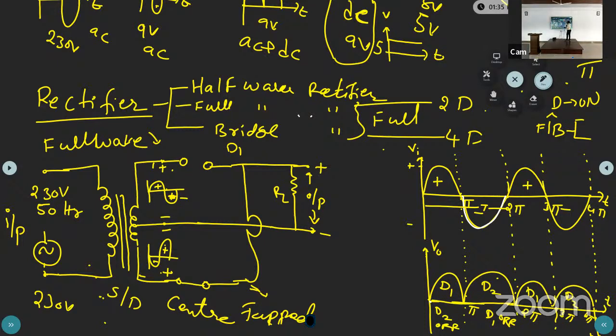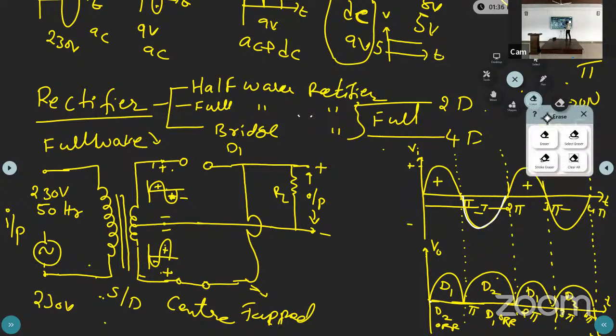Now you can note down this circuit diagram, the full wave rectifier. The output of the full wave rectifier and the bridge rectifier is the same, and all the remaining parameters are the same for both. The parameters are the DC voltage, RMS voltage, efficiency, and the ripple factor. The ripple factor tells how much AC component we are removing at the output side. That is called the ripple. Okay, efficiency. What is the definition of efficiency?